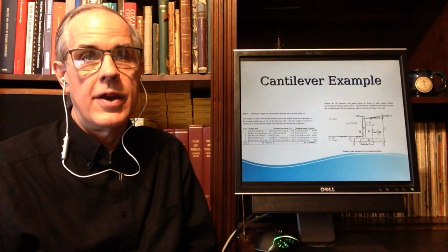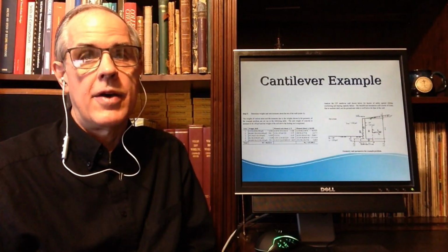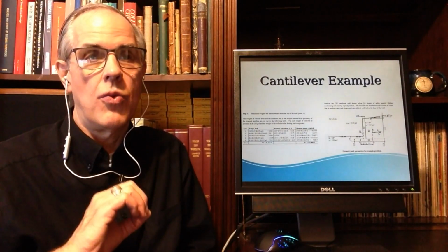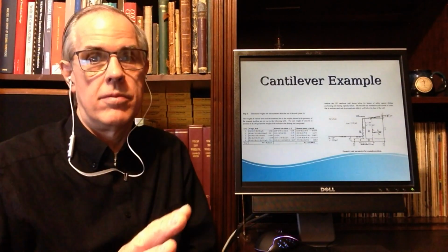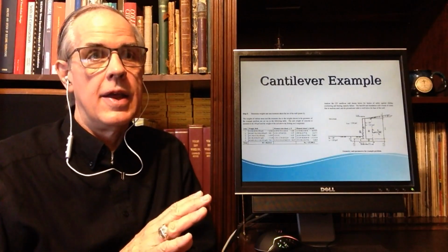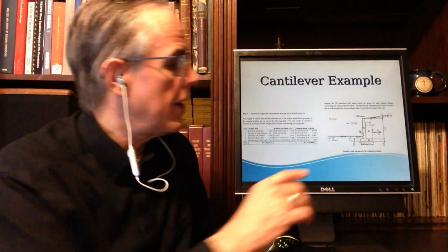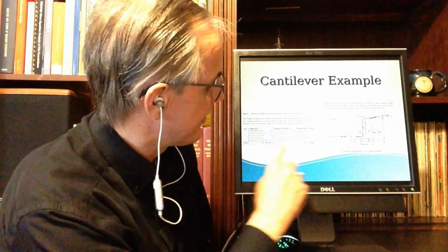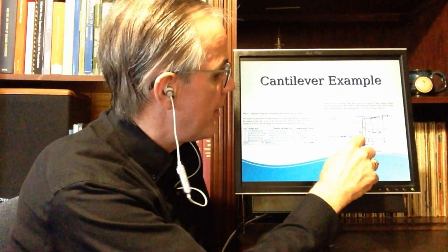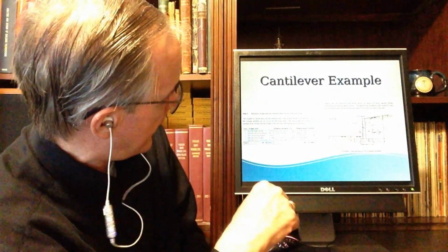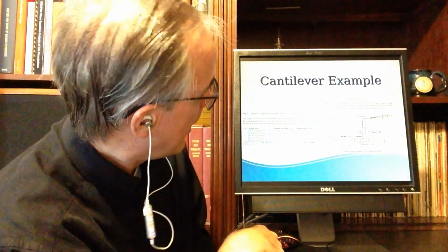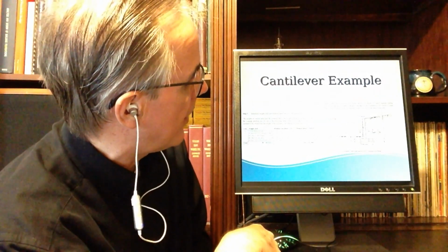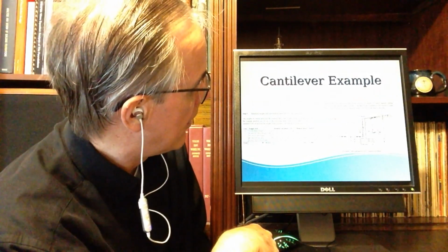And if they have an area, they have a unit weight for that area. They have a weight per foot of wall. If they have that, and they have a centroid, then they exert a moment around here. And that's what all these calculations are all about: the net moment around this point. In fact, all the weights exert a counterclockwise moment around A.